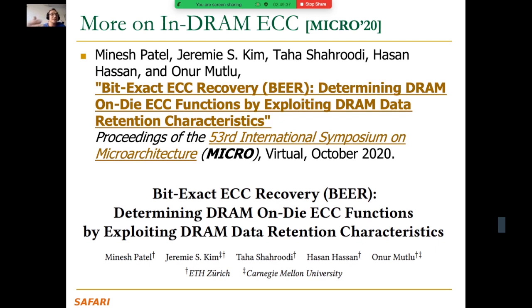So actually, reverse engineering error correcting code functions is really interesting. First of all, you want to enable techniques while somebody's not cooperating, in this case, DRAM manufacturers. That's one good reason for reverse engineering. The other reason is actually to find out the vulnerabilities in the system, because error correcting codes have been posed as protecting for rowhammer, for example, by the DRAM manufacturers, but they're actually not very good at protecting against rowhammer, and reverse engineering them and understanding them actually are very beneficial.